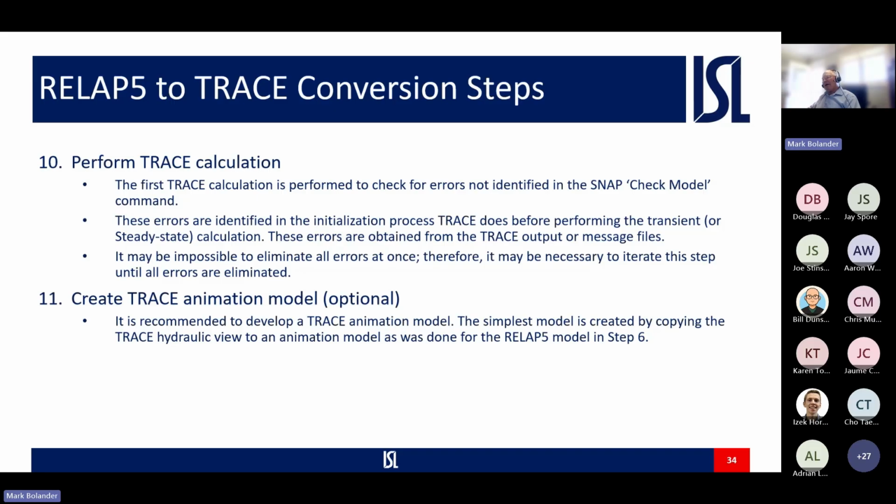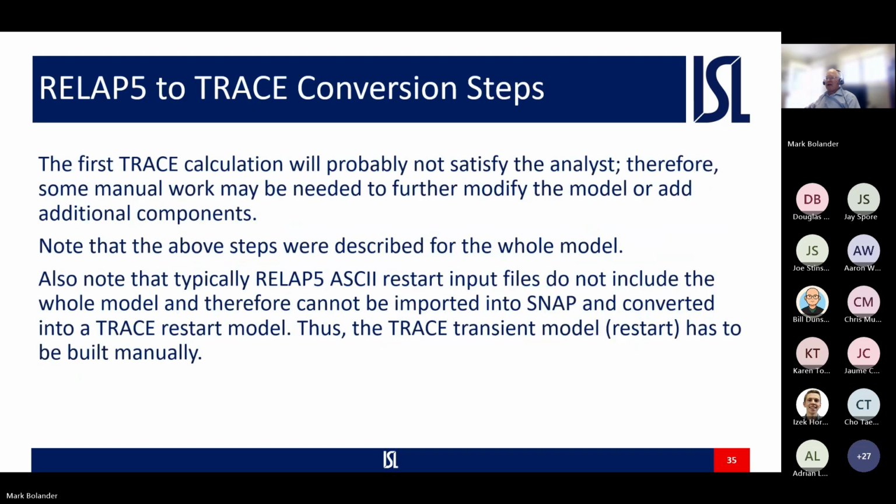And again, it's optional but recommended to develop a TRACE animation model. It's simple: just go in and copy the TRACE hydraulic view and paste it into the animation model. Note that the first TRACE calculation probably is not going to satisfy you, so some manual work is probably going to be needed to further modify your model or add additional components.